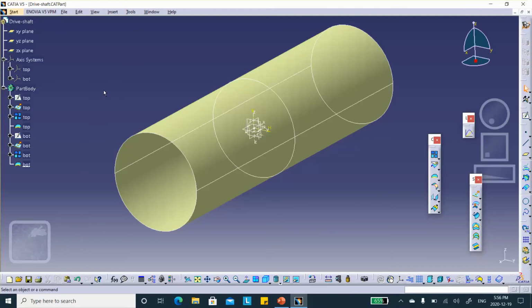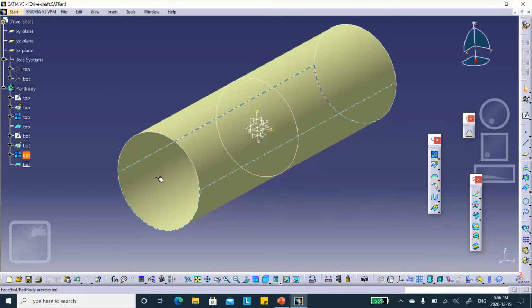Okay, so where are we? This is all done now. I will create two points, one at this end, the other at that end. It makes it easier if I apply my load. You can apply the load by, for example, fixing that end edge, clamping it, and applying a torque to this front edge.